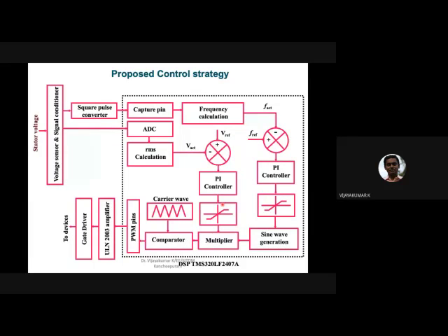So then that will be compared with the carrier wave. Then it will give the PWM. So that PWM you can give to your devices. So why have we used this lookup table method for SPWM? If you are taking the feedback